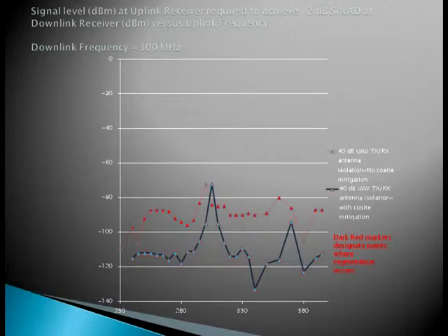This issue is regeneration, which is observed at virtually every uplink frequency without Cosite interference mitigation. Regeneration occurs when the downlink transmitter's carrier and noise energy, once keyed by the uplink receiver sensing a receive signal, is sufficient to continuously key the downlink transmitter through leakage to the uplink receiver.